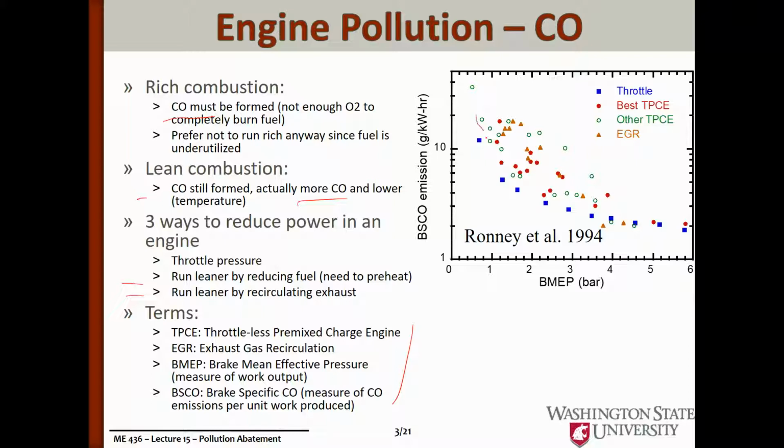And the biggest impact is as you throttle the engine. You're getting less CO, but on a per power output of the engine, you're actually getting more CO at a low power ratio, which is the opposite of what we want.